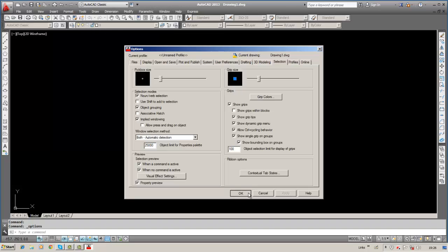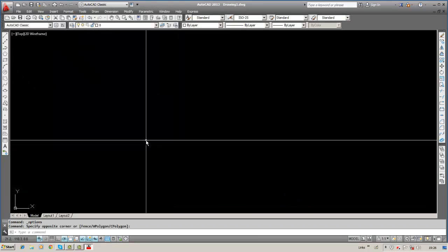Apply, close. Now we have learned about various options we can select. To sum up: color selection, font selection to be printed in the command line, aperture pick box size, and which release to save as. Now we are fairly ready to go ahead with other things.